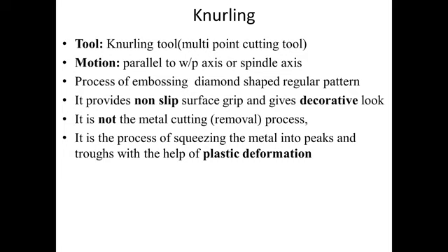Again the motion of the cutting tool, that is the knurling tool movement, is parallel, longitudinal to the axis and the shape is embossed by using the cross slide. Here a diamond pattern, a regular pattern, is impressed in case of the embossing operation.